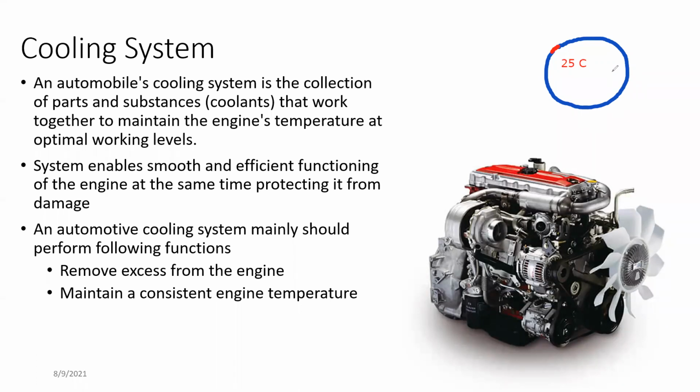So this temperature has to be maintained. Until this temperature, the engine actually has to increase the temperature. After it comes up to this temperature, it should not exceed it, because if it tries to exceed this temperature, the expansion is now outward, right? There's no way to expand, which results in the compression or piston rings getting stuck in the cylinder wall itself. So to avoid that, the engine has to keep a constant temperature, also known as optimum working temperature.